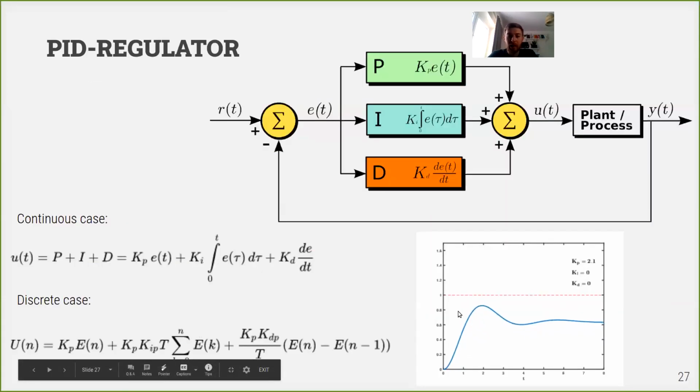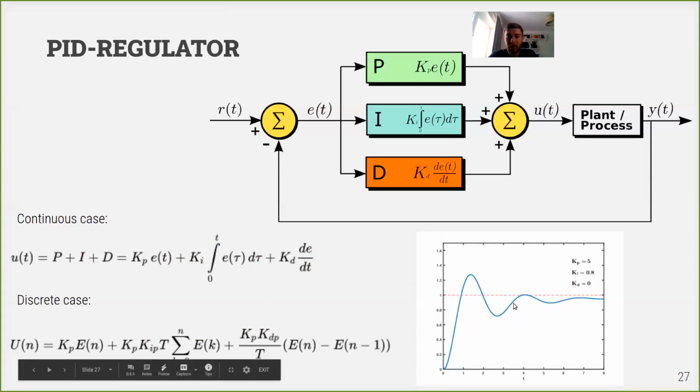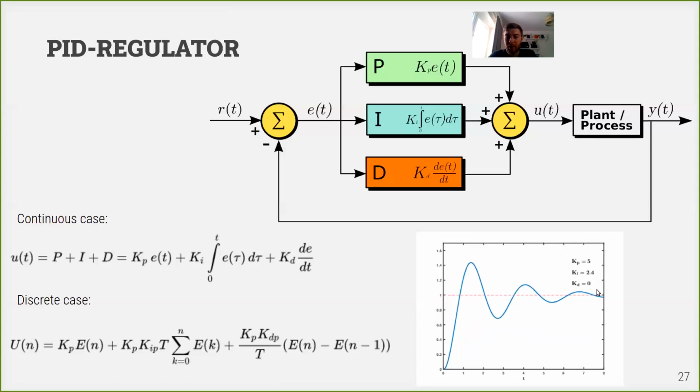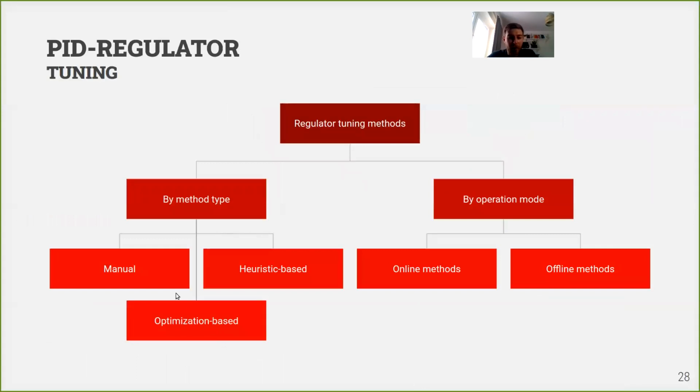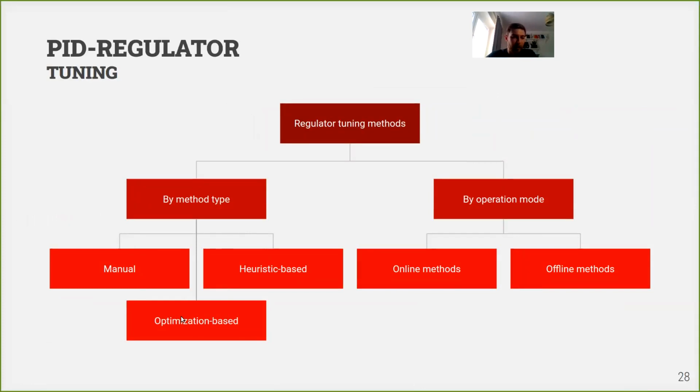For example, we can compute an error, like an integral of the error for the whole transition process, and then we can, with some optimization method, change these coefficients by trying to minimize this error. This also works. But unfortunately, all these methods, which assume that you have a real system and you can measure the real output, don't work for really complex or expensive systems.